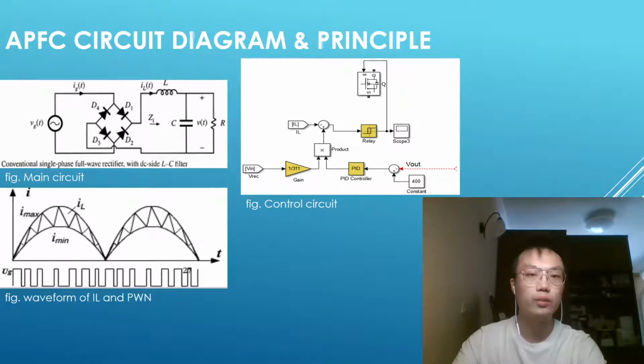Moreover, in this control mode, the conducting time of switch S is constant, but the shutdown time varies. Then the switching cycle is not constant. The bandwidth of the hysteresis device decides the size of the ripple, which can be constant or in proportion to the instantaneous average current. According to the principle, the controller circuit is designed as below.